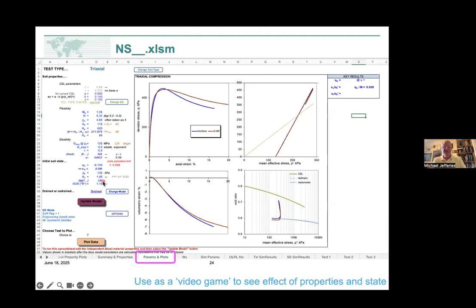There we can calculate the test. You don't have to start from isotropic. You can kick in a K0 if you want to use an anisotropic test. And you can also add in a little bit of overconsolidation if you'd like to. All overconsolidation does is make the initial part of the loading elastic. And this is an example of the fit you should find.